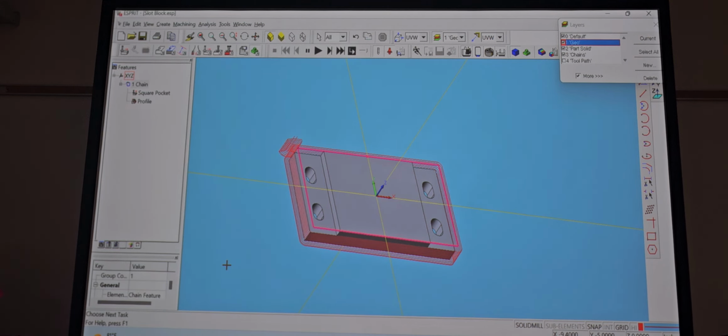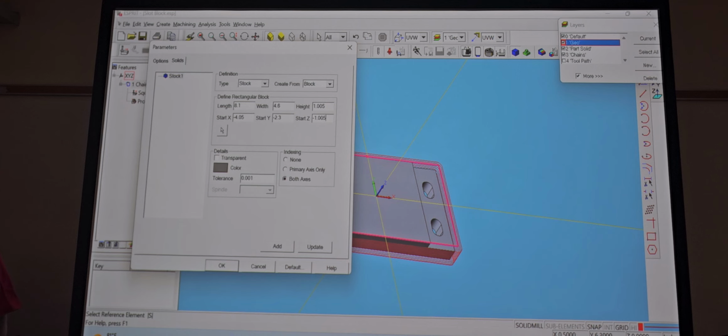What if you faced off 5 thousandths? Then you're gonna be under an inch. No, you're gonna be under. Your price is gonna end up at 995. Yeah, under an inch, but only 5 thousandths. It's gonna be 0.005, and it's gonna start at negative 0.005. There we go. Otherwise it's gonna cut it too much. Minus 5 points.